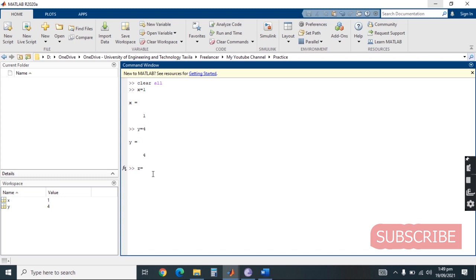Let's say z is the sum of these two variables. We shall make it x plus y. On pressing enter, you can see the workspace also stores the result of the addition of x plus y, with the value of 5. So, it means that the user can use Matlab as a calculator. Let's perform other mathematical functions in our command line window. X minus y.